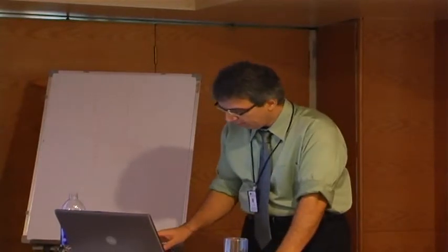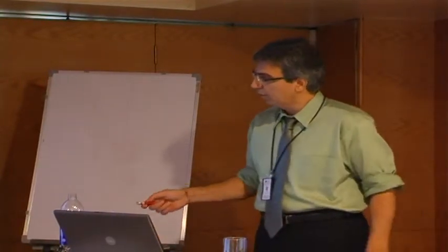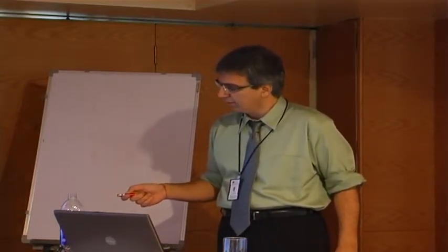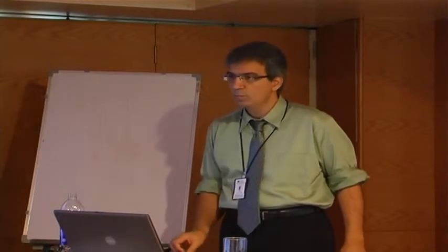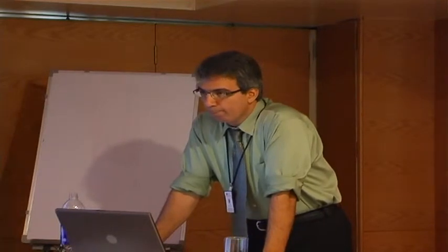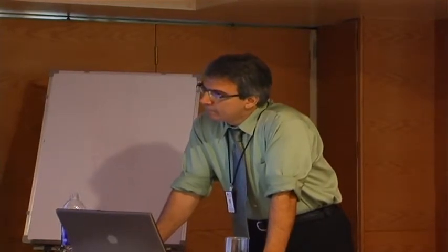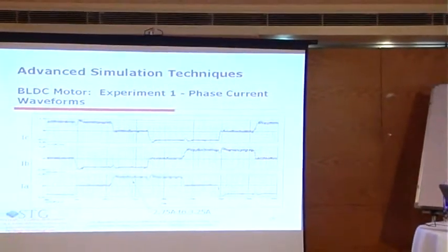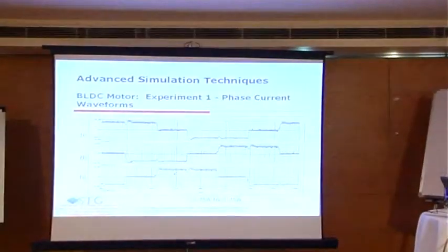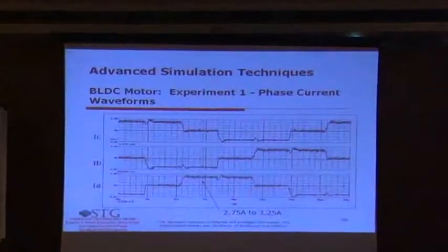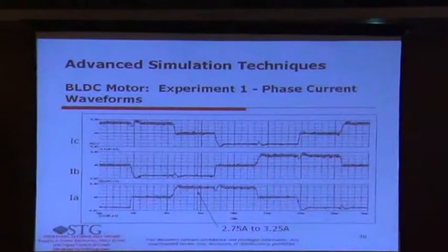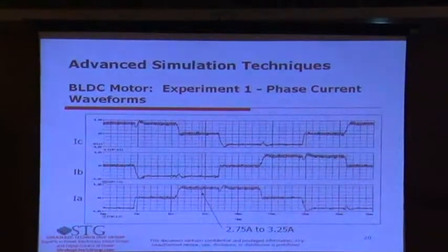Okay, so here you have a motor with about 242 microhenry of inductance. But the delta I depends upon L, right? If I take delta I by delta T equal to VDC by 2L, then delta I is proportional to 1 by L. So the ripple of the current will be inversely proportional to L. Yes, so that means my ripple will be dictated by the inductance value. Your ripple, yes. But not the dip.